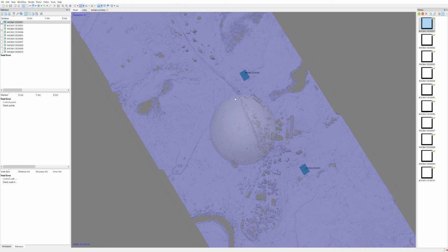So I'm going to run it on low and use this height field of 2.5D. 3D would retain all surfaces in three dimensions, so the floating points would be all connected together, and any overhangs or anything like that would be retained. 2.5D is like a DEM, where at each XY point the highest value is considered the height, and that's it. That'll save us some space, so we're just going to run that and press OK.